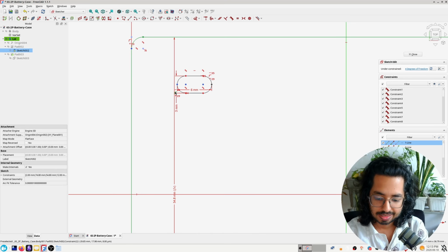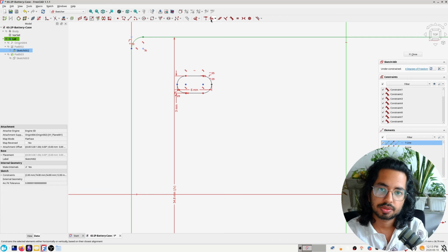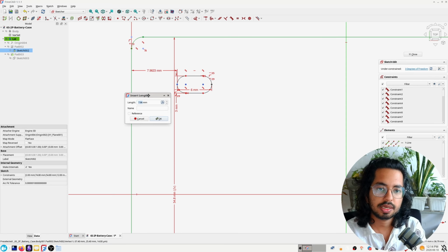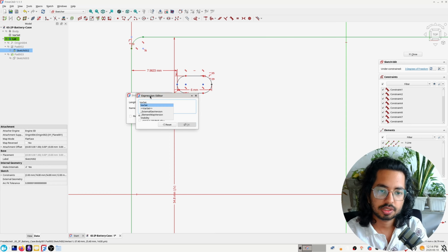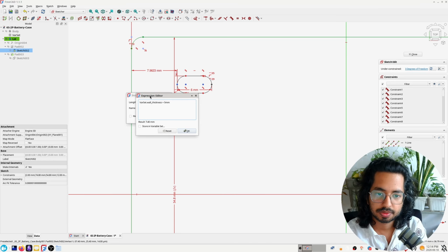Okay, KD, sorry, we can't do KD here. What we can do is the length. If I press I, I'll get vertical, and if I press L, I'll get horizontal. So I pressed L, and how much do we want this to be away from the wall? We want it to be a bit further than the wall, equals to var set wall thickness plus, let's say I want to add 5 mm of gap.